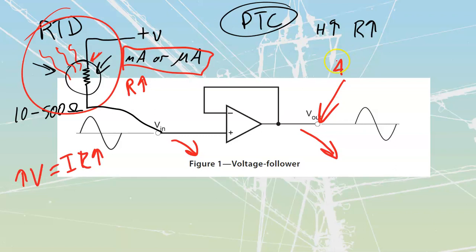So anytime that we need to drive out more strong current, maybe for a proportional valve or something like that, where you're adjusting the flow of glycol in a system or anything like that, you would need to use one of these op amps that's going to be able to deliver those actual amps through here. Read on the inside over here as a voltage, deliver those out over there.